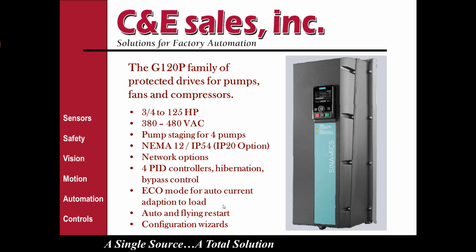It does have the eco mode, again, like some of the newer drives, so you can adapt the current to the load. And it does support auto and flying restart. So if you have large blowers or fan assemblies with a lot of inertia that you want to come online with after they've been turned off but are still moving, you can do so without causing an abrupt change in the control of them.